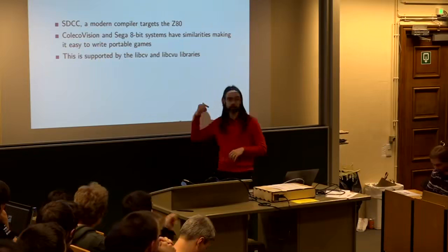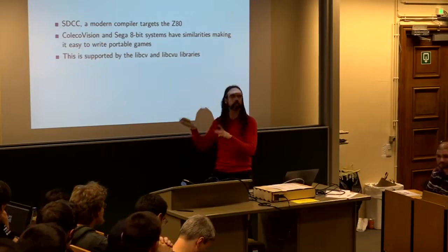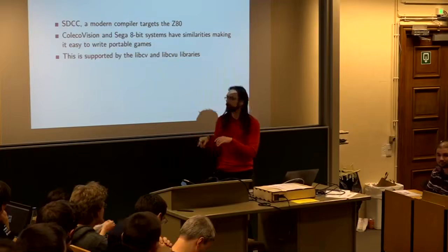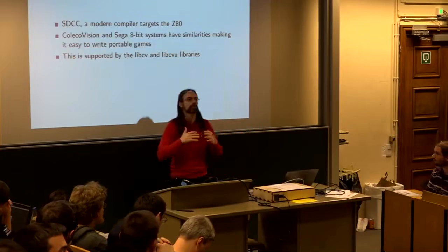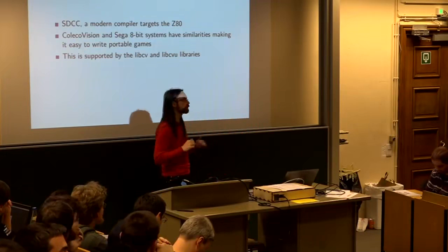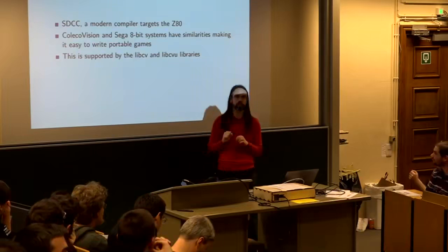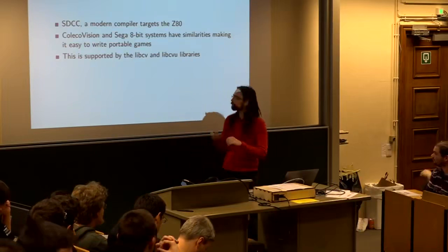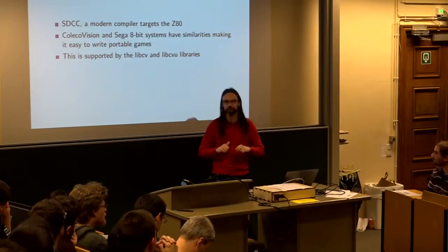SDCC gives debug output on other targets like modern microcontrollers like the STM8. You can do on-target debugging with that. But for those old systems, there's that one emulator that I know of that has debugging support, but it's a bit odd to use. They even use their own basically Windows system, and it looks like in the DOS days. But you can compile this emulator on modern Unix systems and use it.